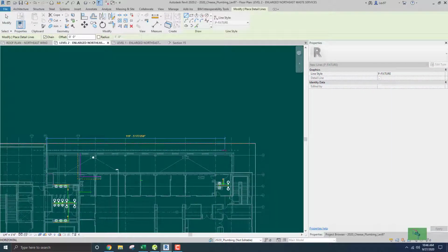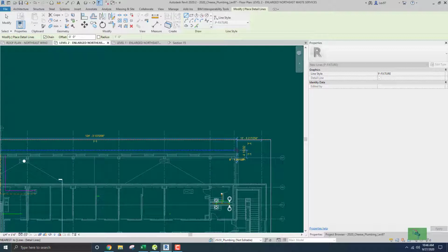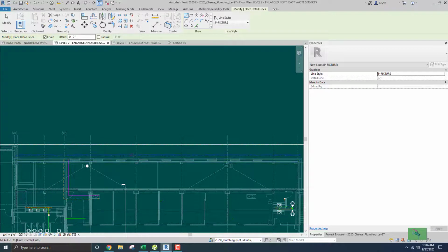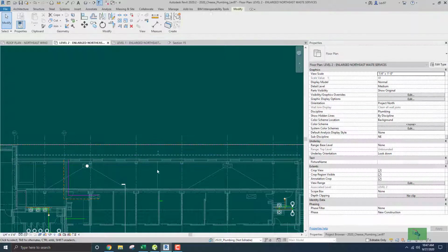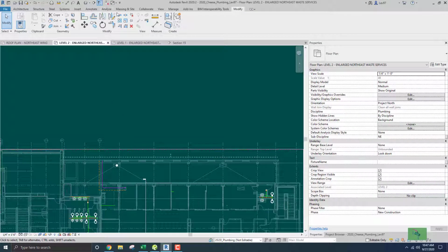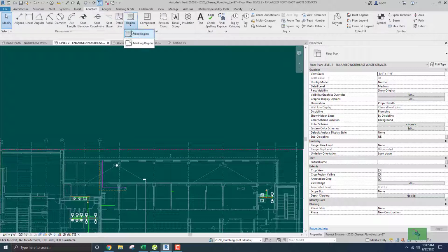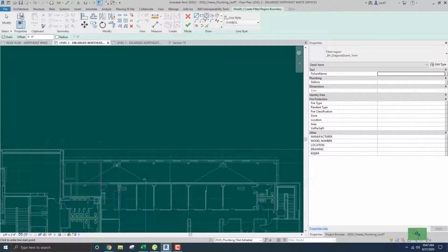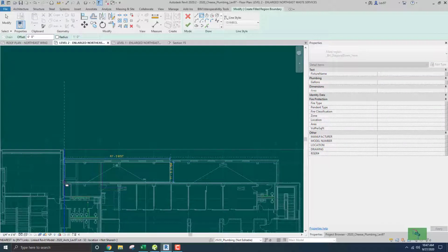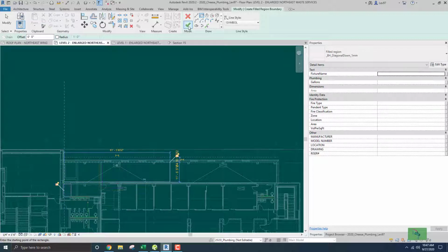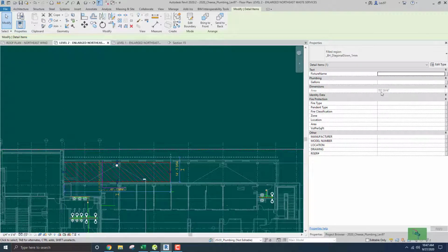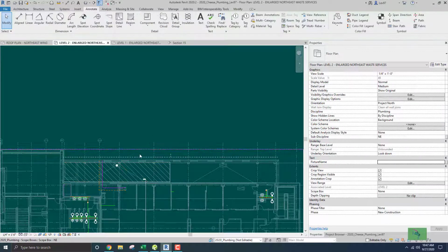Let's go over to about right here and get our midpoint is about here, okay? So we go back and annotate the region, get our rectangle, start maybe about right here. We can eyeball it to about right there. And we can see that it's about 710 square feet, okay?